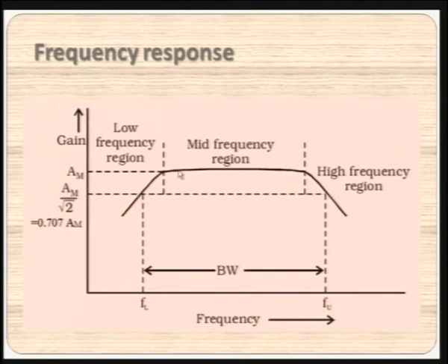But when we are ready to lose the gain by a value, because of the trend that we have, the frequency range is getting extended. When we consider this as the reference line, the reference line cuts the graph at 2 points, which are beyond the mid frequency range marked here, keeping only the frequency in mind. So, the bandwidth is extended. See here, on either side it is extended.